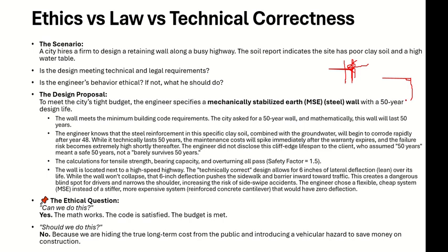So you can imagine what can happen to the drivers. The drivers may go into this bend, and they may have accidents. This bend may be blocking their line of sight, their sight distance, and so on and so forth. And obviously when this bend is happening, nobody will get close to the wall, so the last lane and the shoulder will be useless. Nobody will go close to the bending wall. Now your design will not show these things. Your calculations are correct, but these are the problems which you will have in future.